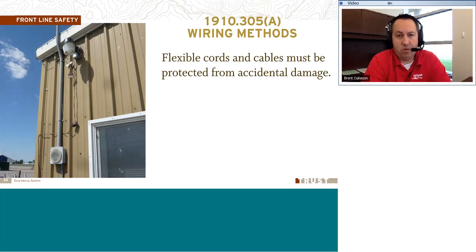So with flexible cords and extension cords, things like that, they need to be protected from accidental damage. A lot of times they get nicks and cuts in them. Sometimes it can cut into the interior insulation of the wiring, and you can get some of that copper wiring exposed, and that can become a real problem. So always inspect those things. Keep them free from contact, free from sharp edges, free from things that could open them up and cause a problem there.